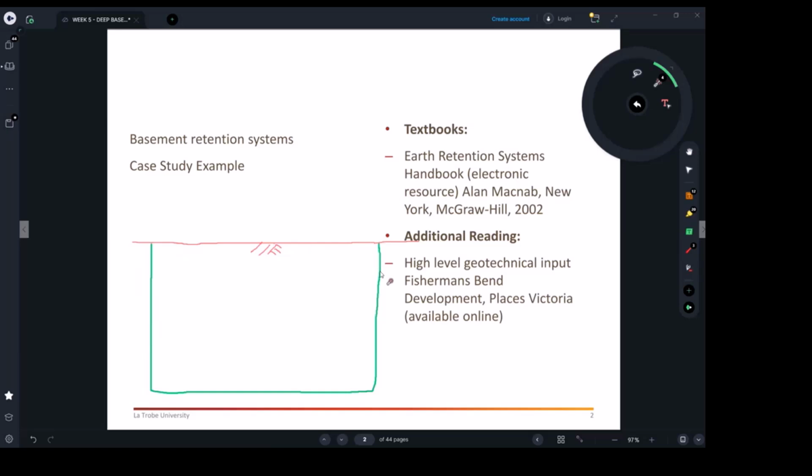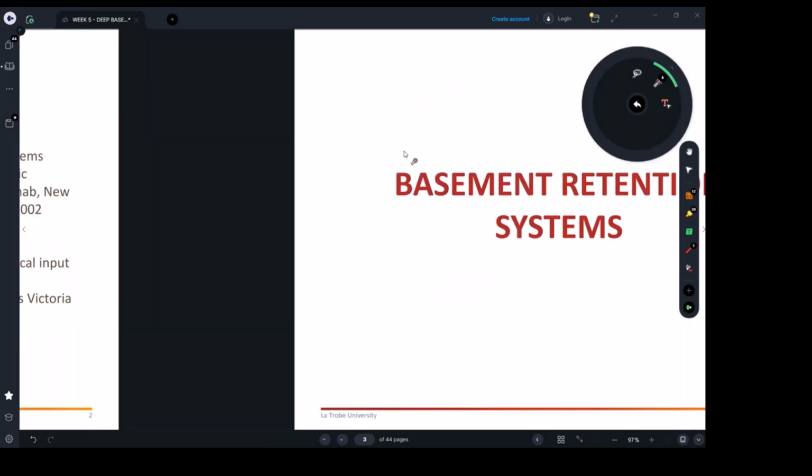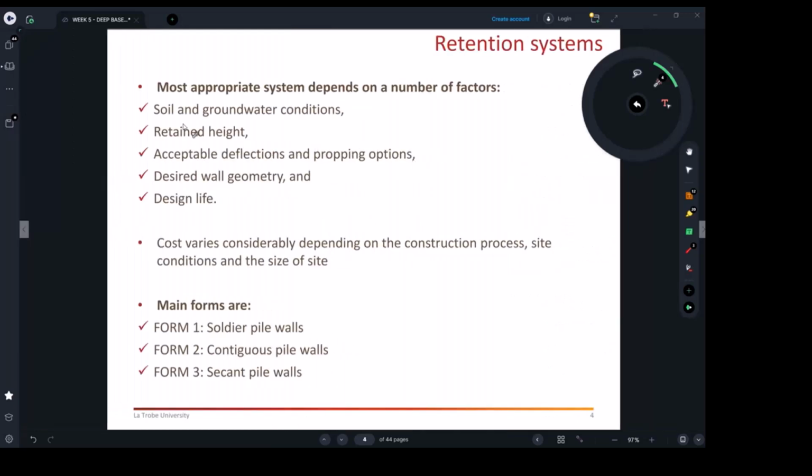The big challenge, and that's what we're going to discuss and think about, is if you have a building next door. If you have a building next door and you want to excavate, now you have two troubles. It's not only about how stable the soil is, it's what we're going to do about the neighbors, the next door property or building, which we will discuss. So the first factor here is soil. The second one is the groundwater.